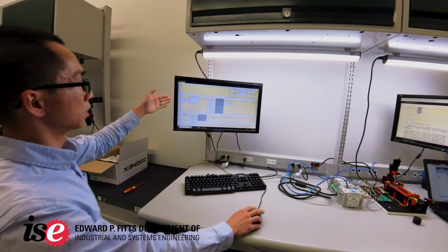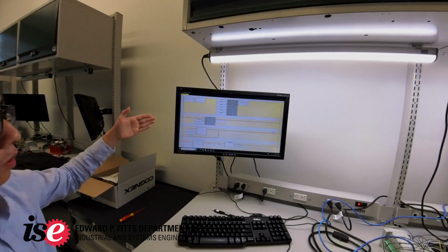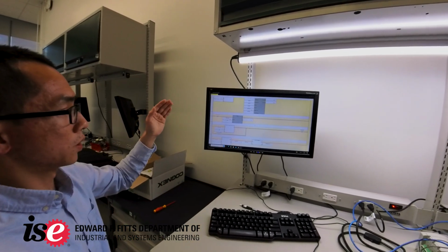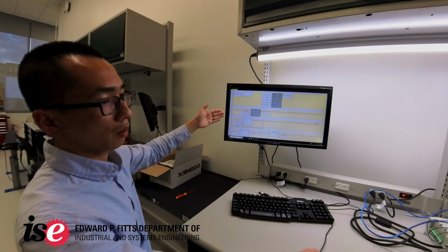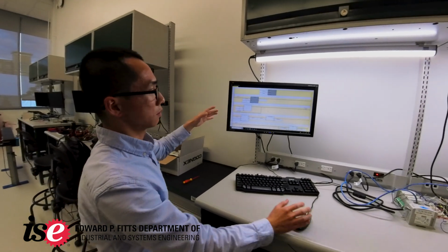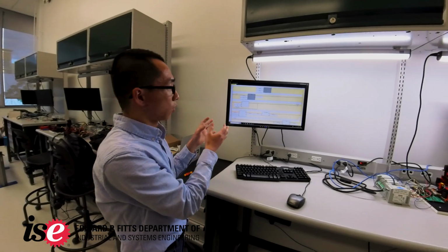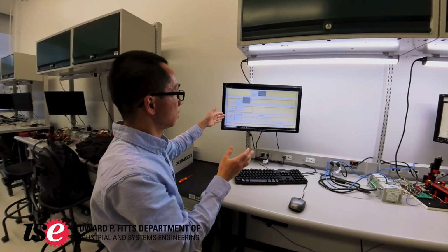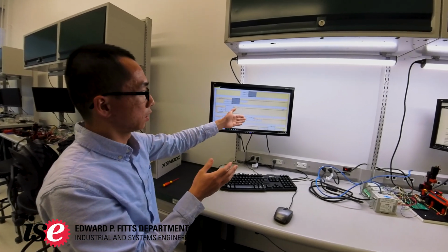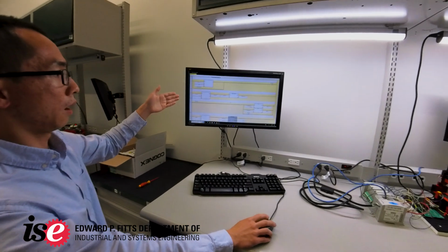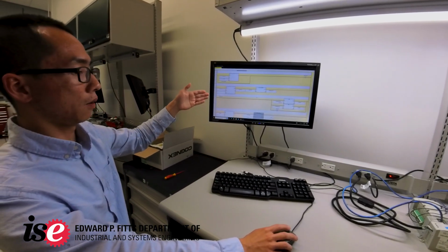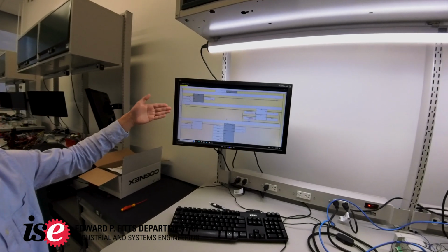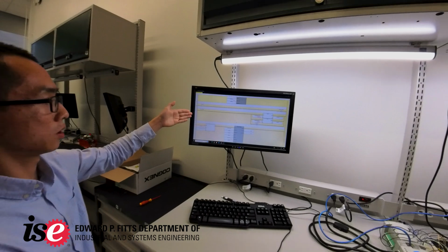And the next 2 lines are to count how many items have passed through the conveyor belt. So we set a counter here, and we set the maximum number as 100, because the CCW has a default variable that the number will begin at 0. So we add the process here, and we change it from an integer to a string, which can be published through the MQTT publish function. So the next one is to publish the count, and the next two are to publish the default speed, and the next two are to publish the slow speed.